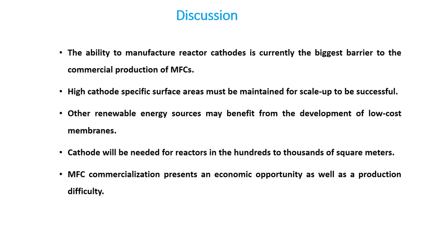Finally, the discussion section. In the near term, the most promising microbial electrochemical technology, MET, applications will likely be microbial fuel cells, MFC, for wastewater treatment, as these systems lack expensive membranes and can accomplish removal of organic matter without aeration, and sediment microbial fuel cells as remote power sources. Successful scale-up will require maintaining high cathode-specific surface areas to maximize volumetric power production and organic matter utilization rates.